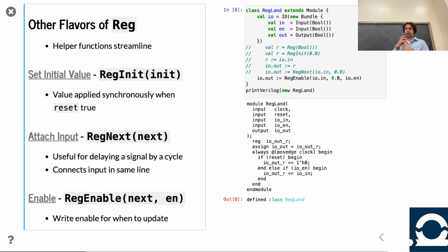The question is, if I create a register in Chisel and I care about the Verilog output, will it always produce an always block? Yes, the way in idiomatic Verilog to create a register is you have these always blocks and you have the Verilog tool infer via synthesis that there are registers there. Perhaps your company has their own special optimized registers you want to use.